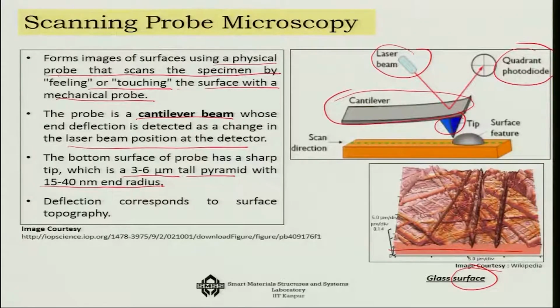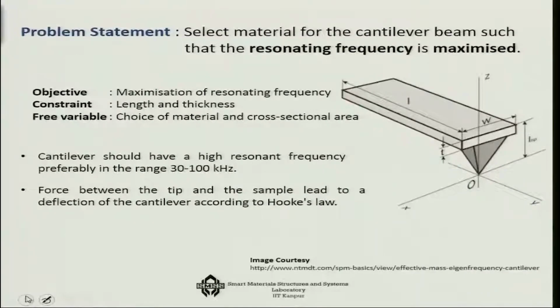It is very challenging. In fact, that bottom part of the system is, you can say, a MEMS or a NEMS device on its own. It is a micro electromechanical or nano electromechanical system, and naturally the deflection corresponds to the surface topography. So, our tip has to be very fine, and whatever little deflection is produced has to be interpreted in terms of the surface roughness. That is the idea for the scanning probe microscopy probe.